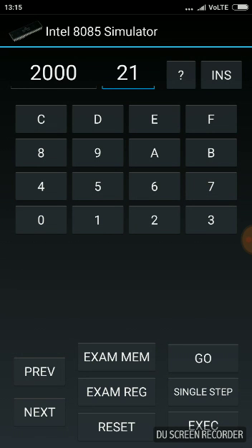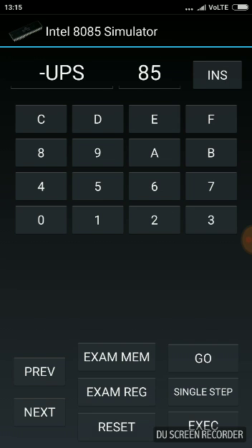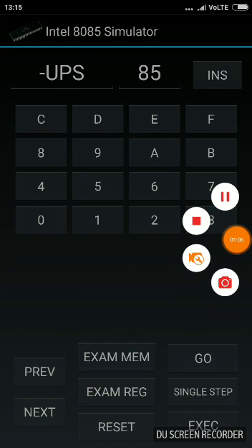So here we would use the LXI instruction, which basically loads a memory address into the register pairs. Further, we would also use the MVI instruction, which immediately moves data into one of the registers to set up a counter. Then we will also illustrate the use of the jump instruction using the zero flag, and we will set up a loop. So let's go about doing this.